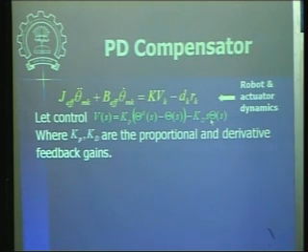The final desired velocity is 0. You have subtracted the actual velocity of the motor, s theta s, the actual velocity of the manipulator or motor joint, and then you have used it as another term in your control expression. So this is called proportional and derivative feedback. So in simple terms it's called a PD compensator, okay.